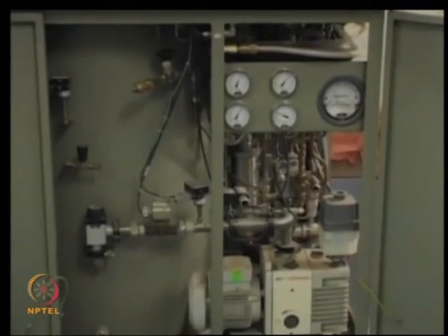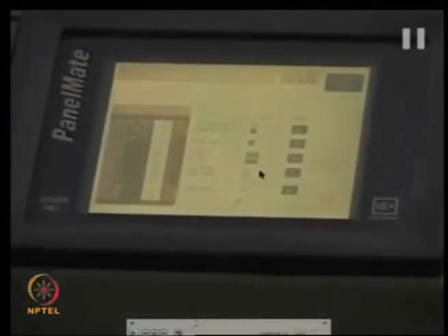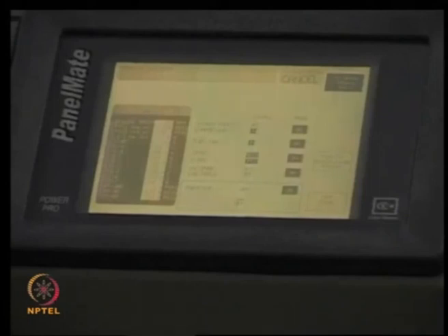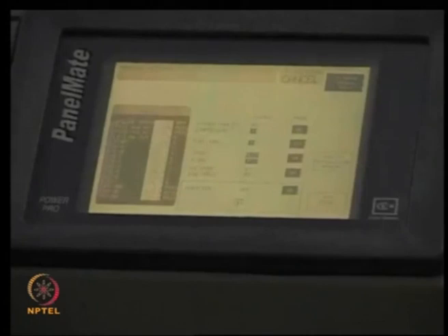Okay. So, just have a close up of the machine, and what you see now here is some display. You can always see what the temperatures are at various points in the machine. For example, the inlet temperature, the JT temperature, or the gas temperature before the JT expansion. Also, what you can see is the RPM of expansion engine number 1 and expansion engine number 2, and things like that.